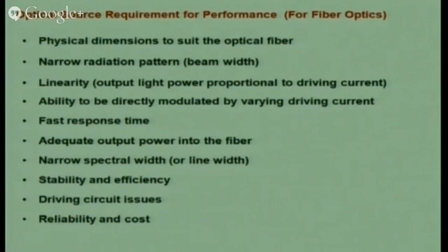Then there is the ability to directly modulate the source, because I want a modulation phenomenon to take place on the light which I make propagate through the fiber. It can be analog modulation or digital modulation. If the source is linear, then the modulation is linear and I can detect in a linear fashion. Otherwise, nonlinear components will come in. Then fast response time: when I change the current, it should immediately switch on or off, either in an analog or digital fashion.